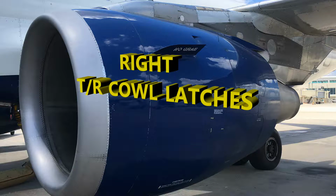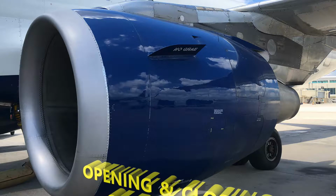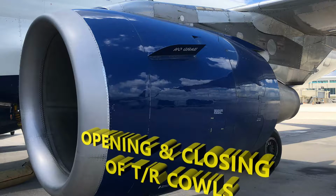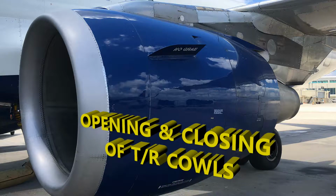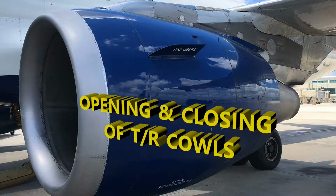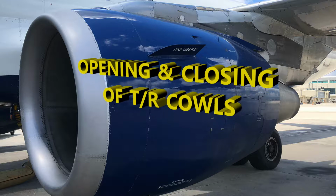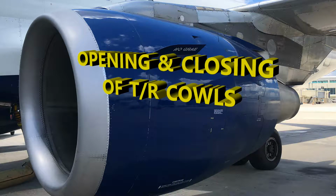Now, the opening and closing of the thrust reverser cowls, there's, like I said, a sequence. You don't have to memorize all of it, but just remember you've got pins that you need to remove before moving a handle, not for all of them, just for some. And then you've got to install a handle pin, and then put the extension into the end of the handle, and then release the over center lock trigger. So there's a trigger that you'd have to release. I mean, there are different methods depending on which latches you're opening. So that gives you an idea.